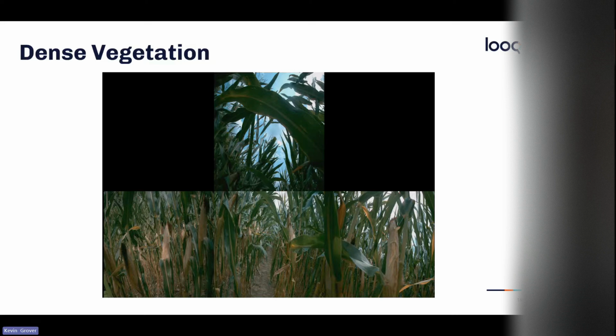So this case was probably a cornfield, impossible to reconstruct. So you want to remain away from the vegetation. We have about a 1 to 3 meter buffer that we want to stay around. You want to walk in the areas where we know we'll be able to reconstruct, where you can still see the pole information, the overhead lines, but avoid walking through dense vegetation like this.